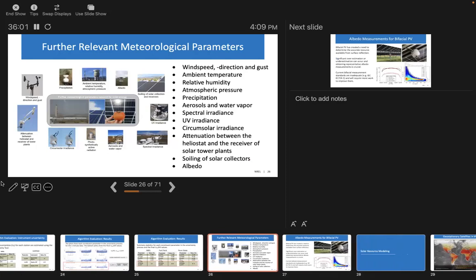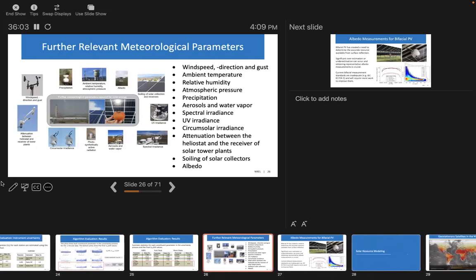Again, like I said, we don't only measure solar radiation; there are all these other things we have to take care of so that a PV model can happen. I won't read through the list, but I'll point out a couple of things. Look at this circumsolar radiation, you have a 5-degree field of view. Normally in a radiative transfer model, when you do direct, it's extinction, like a pinpoint. So you can't measure it. So we have to build models which can actually do circumsolar radiation.